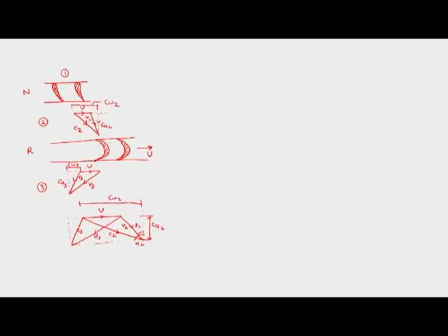So for us this becomes CA3 and then this becomes CW3, and we expect CA is equal to CA2 is equal to CA3. So we expect the velocity in the axial direction to be constant at the inlet and the outlet. Here we can see that CW2 is in this direction and CW3 is in this direction. So this should be remembered, since we would need this.